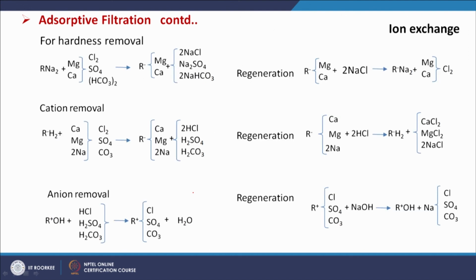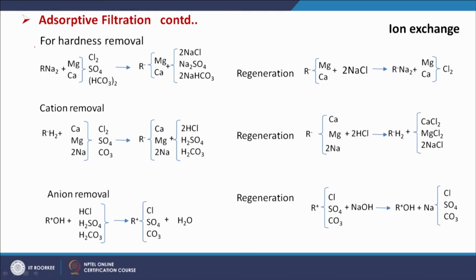Then we see that ion exchange phenomena can also be responsible for the adsorption process. Apart from that, to get more purified water, we use the ion exchange method. As discussed in our previous class on drinking water treatment, for hardness removal ion exchange can be used.